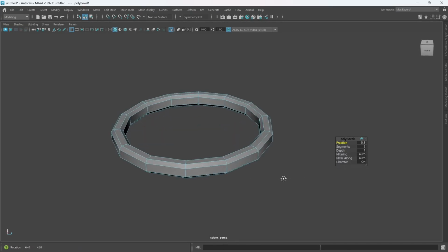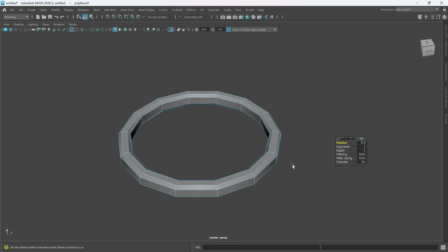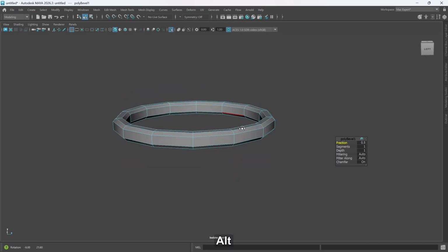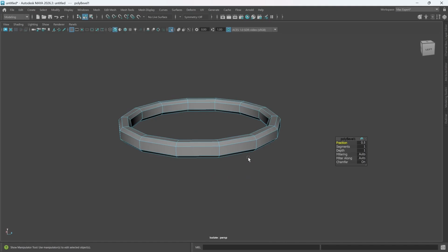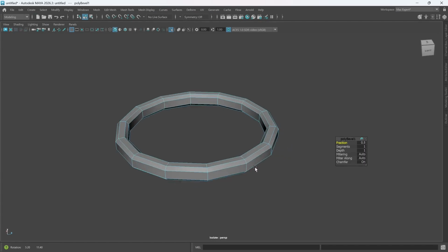And sometimes this is not always the problem. It's going to feel like the problem is the reverse faces, but most of the times you find out that you have double edges at that particular place. So just check the issue you are having. If you are having double edges, make sure you verify that by going into the wireframe and shifting every edge individually. And if you have reverse face, just go ahead and reverse the face.